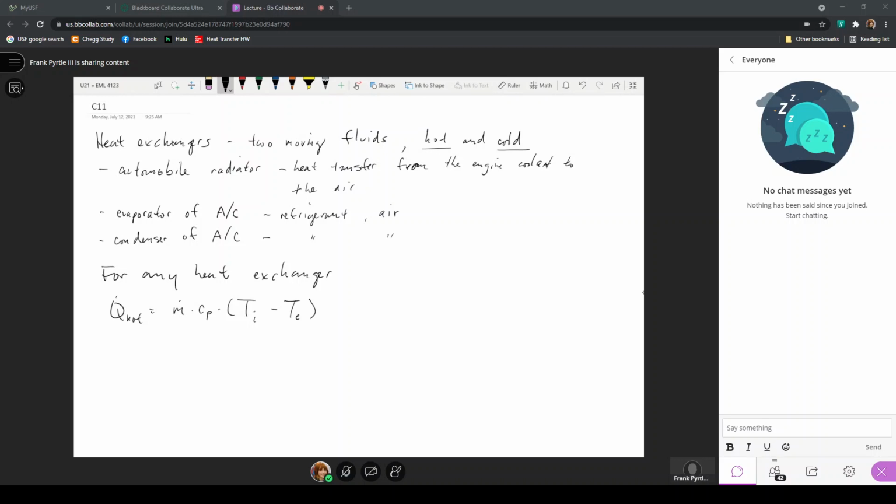Now, with this being the specific heat, for a liquid, the constant pressure specific heat and the constant volume specific heat are actually the same value if it's considered to be an incompressible liquid. Also for gases, usually for a given temperature range, the specific heat will be considered to be a constant, but if it's a gas, the constant pressure and constant volume specific heats are not the same.